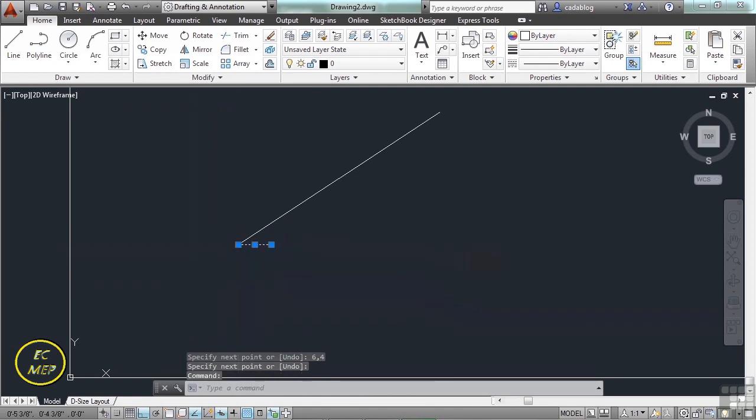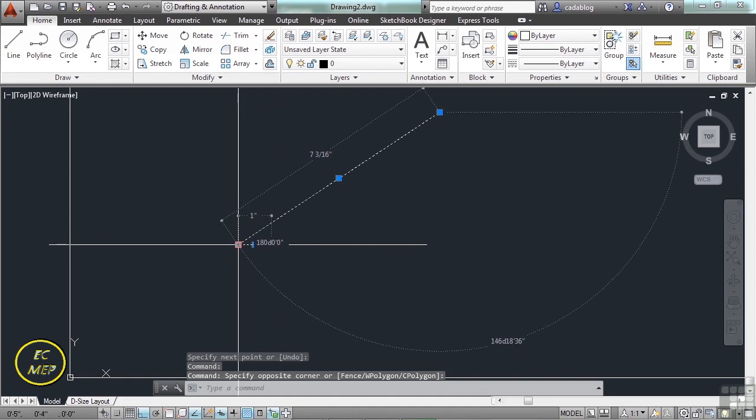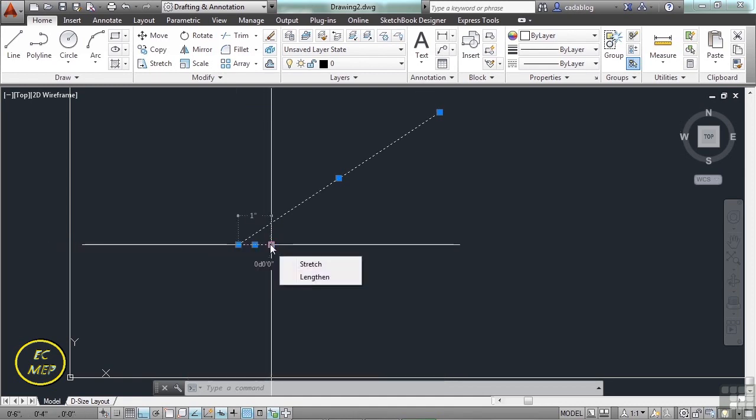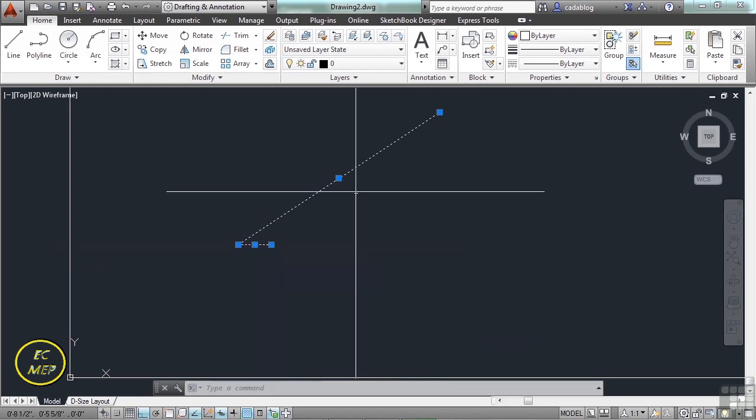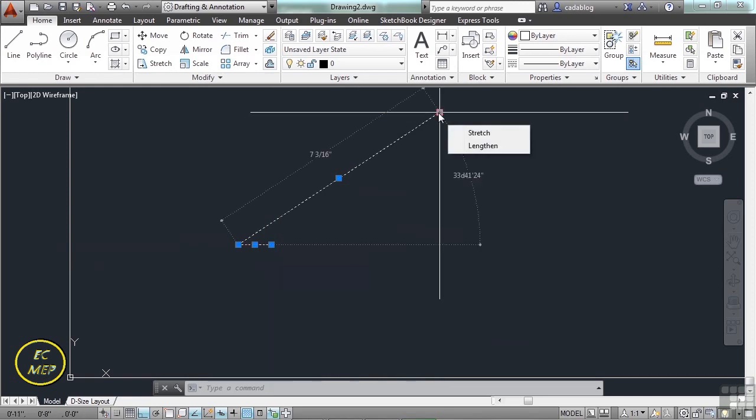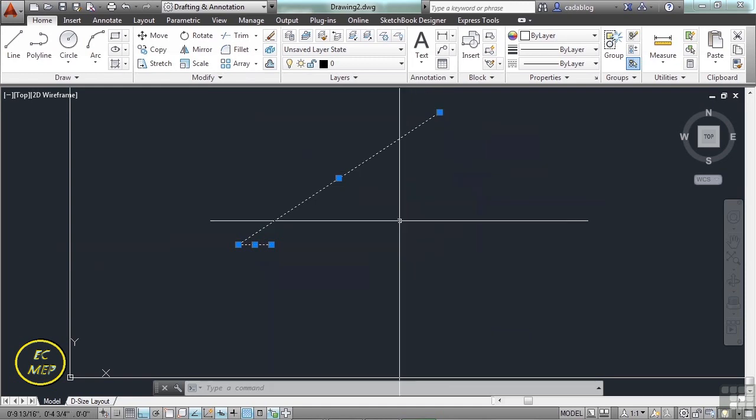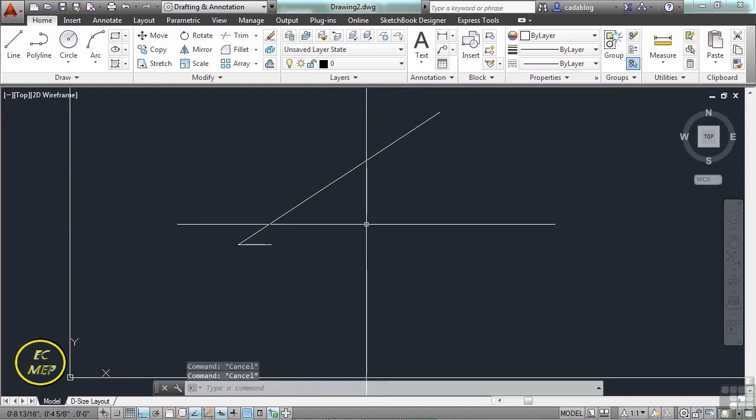This line and this line both start at coordinate 5, 4. Now the coordinate for this one is at 6, 4, which is what we told it to do. Now we told this one to go over 6 units and up 4 units. So it is at coordinates 11, 8. So keep that in mind. A lot of times you will find drawing in relative coordinates useful. If something needs to be 20 feet long or 20 meters long, you can tell it, I want to go 20 units to the right and 0 units up, and you have drawn a horizontal line 20 units in length.